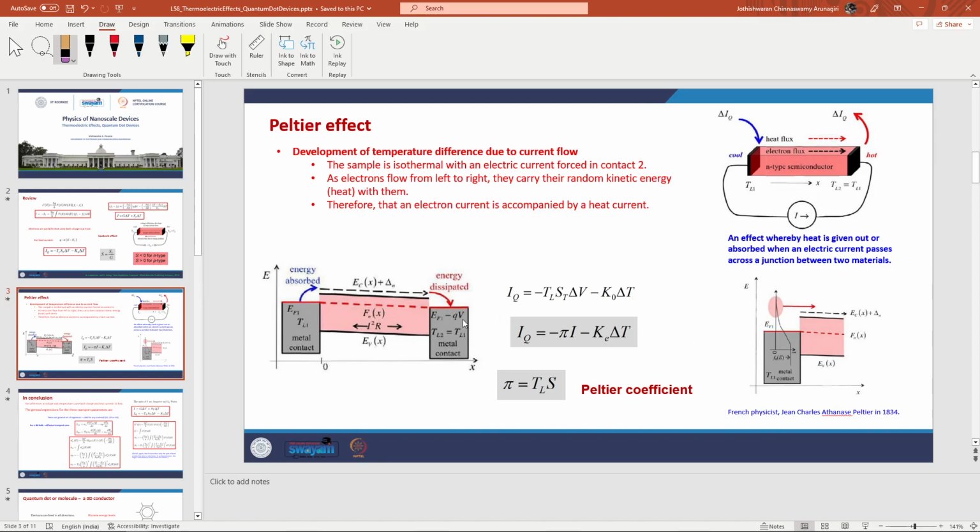So, when we have electrons moving from here to here to enter this channel, it has to dissipate energy, release energy into this electrode, essentially the drain, in order to move into the drain and complete the current circulation. So since it is releasing energy into this region, this electrode will get heated up. Similarly, over here, for the electron to enter the channel, it has to gain some energy, which implies it is absorbing that energy from the lattice.